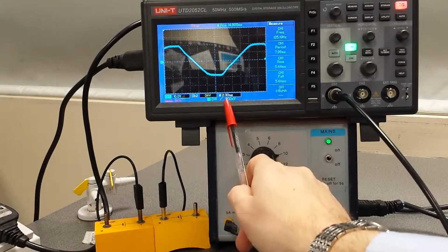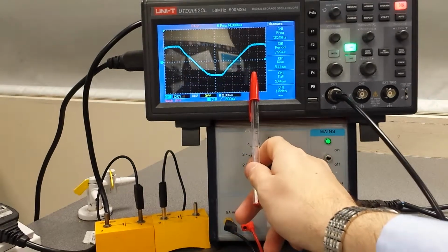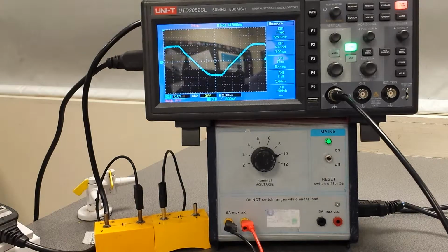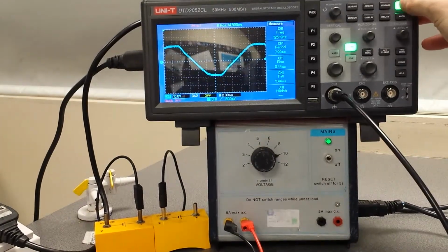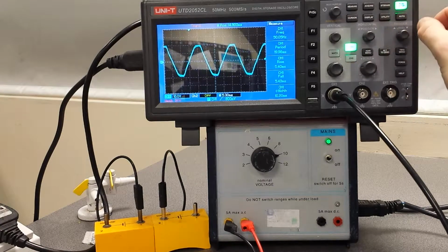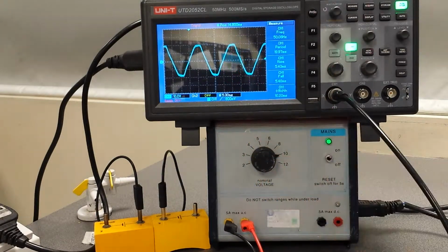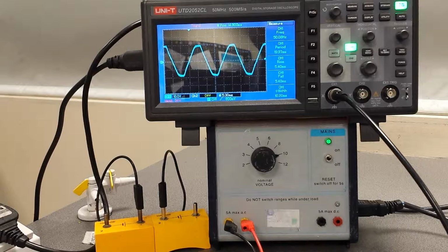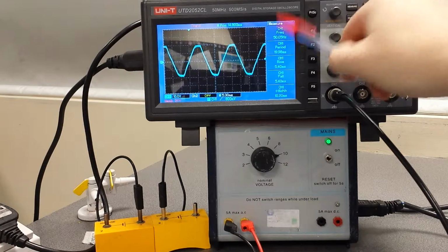Now if it's 2 milliseconds per division, I'm getting 1, 2, 3, 4, 5, 6, 7, 8, 9, 10. There are 10 squares there. Well, 10 times 2 milliseconds is 20 milliseconds. 20 milliseconds is 0.02 seconds. Then if I do 1 divided by time for a whole up and a down, which is a whole circle or a cycle, if we do 1 divided by 0.02, we get 50 Hertz. Now the clever thing with this oscilloscope, it works out that for you. It tells you the frequency.